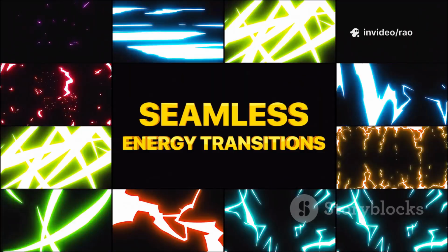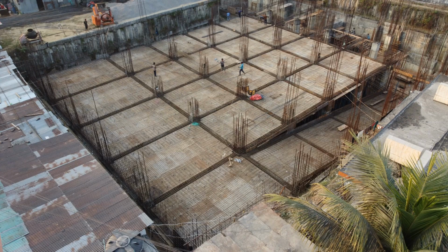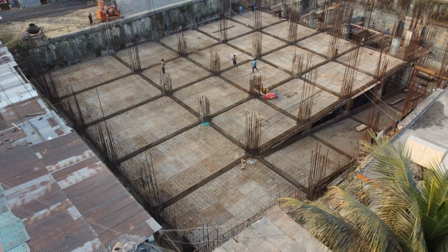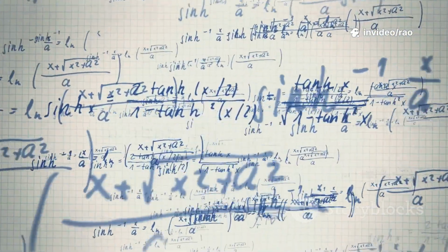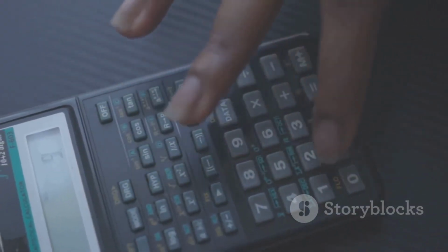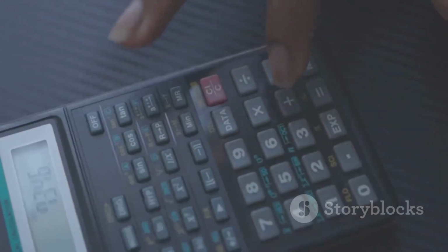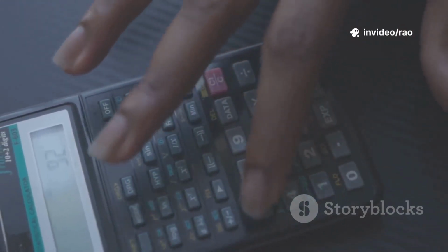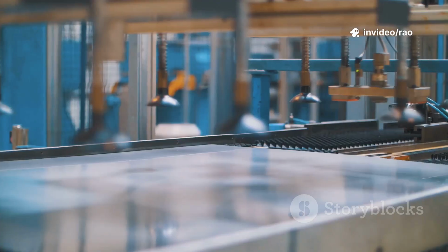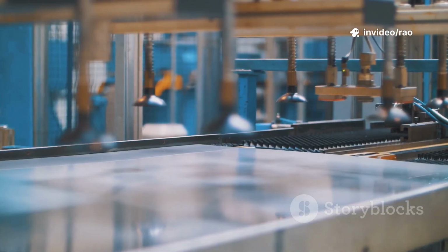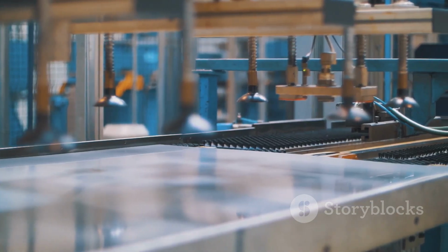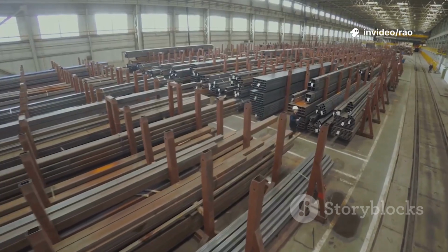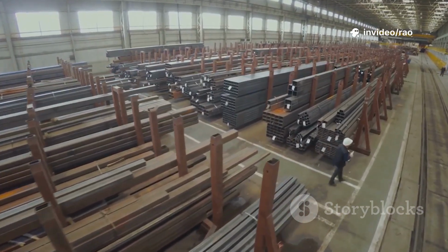Similarly, we calculate the cutting length for a single distribution bar. The distribution bars span the 3,000 millimeter width of the slab. Cutting length per distribution bar equals span of distribution bar plus 2 times hook length. Cutting length per distribution bar equals 3,000 millimeters plus 240 millimeters equals 3,240 millimeters. Cutting length per distribution bar equals 3,240 millimeters divided by 1,000 equals 3.24 meters. Each of the 28 distribution bars will be cut to this length.